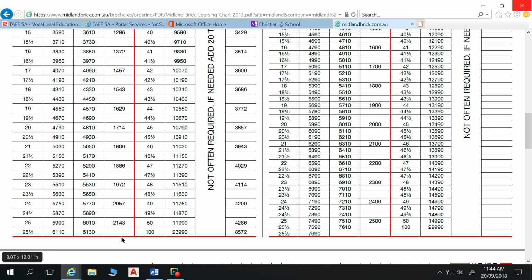So we'll want our walls to be, you know, that 4.31 long before we have a window, and then you've got your standard size doors and windows, and you design your location of all these doors and windows as per your brickwork dimensioning. If you don't, then you have very unhappy bricklayers, because they'll be laying those bricks, and then they'll have to be cutting small bricks. It also looks really bad.